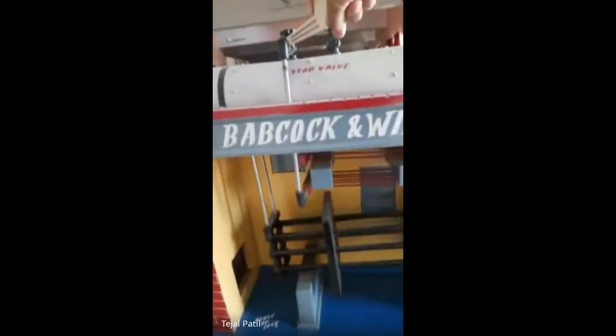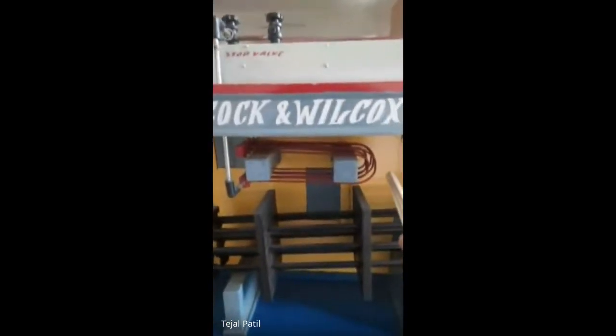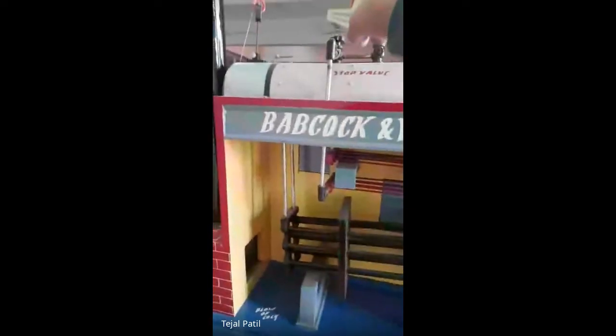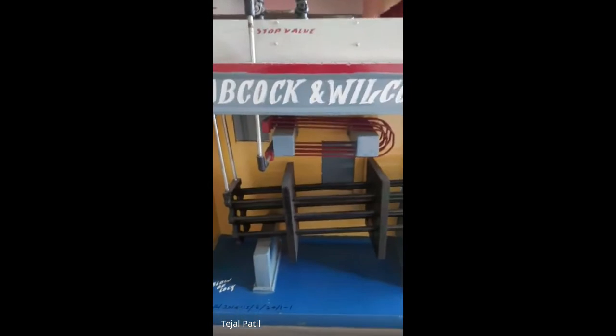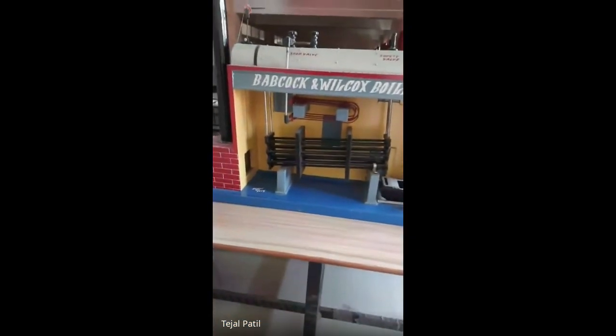to the place wherever required through this steam stop valve. Okay, here is the entry, you can see from here is the entry, then it is going to circulate like this, and from here it will be sent to the outside place wherever required. Okay, so this is what is basically the superheater. In the Babcock Wilcox, the economizer is not shown here, but it is there again.